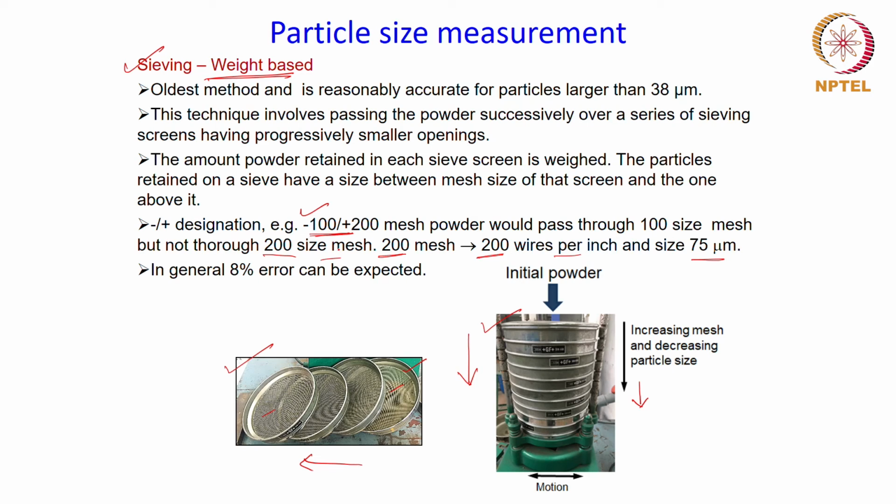And as I said, this is a weight based technique. So the powder is first loaded on the topmost screen that you have over here, and then this whole setup is closed, and then it is given a shaking motion, right. This is the motion direction.